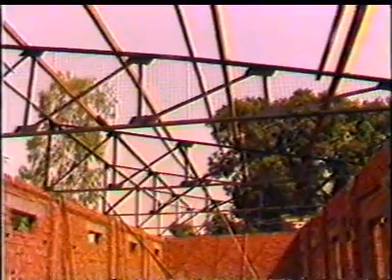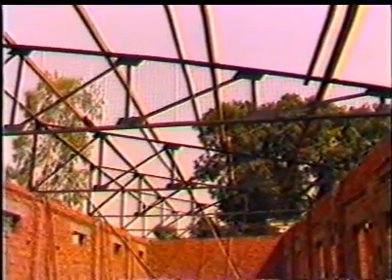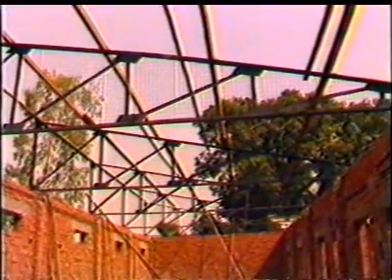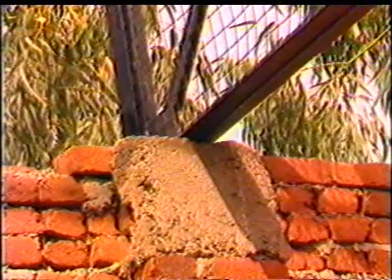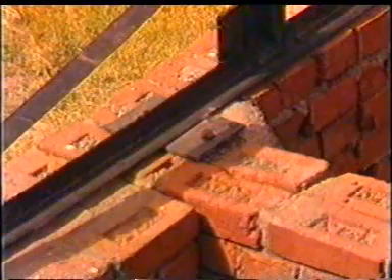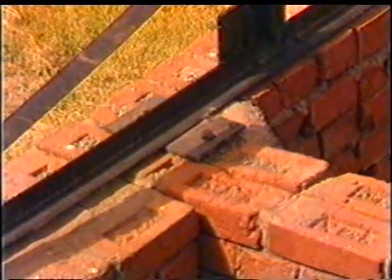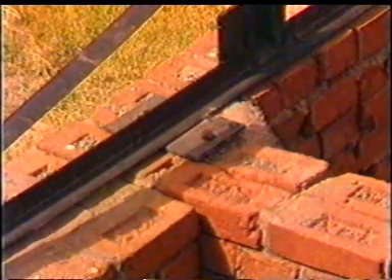The trusses are erected and fixed to the supports. Trusses are fixed on the walls and columns by means of anchor bolts, which are connected with the base plate attached to the bottom chord of the truss.